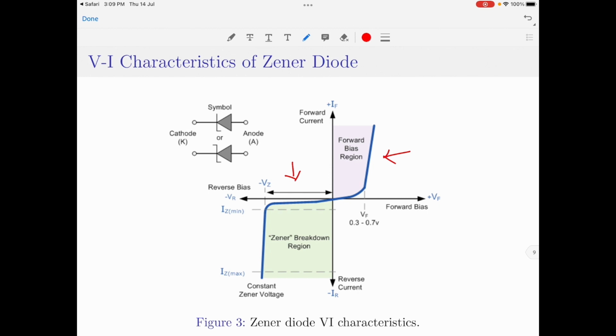These newly created free electrons will also get sufficient kinetic energy due to the same high applied electric field, and they create more free electrons by cumulative collision. Due to this cumulative phenomenon, very soon a huge number of free electrons will get created in the depletion region. This will cause the diode to break down and then it will start to conduct.